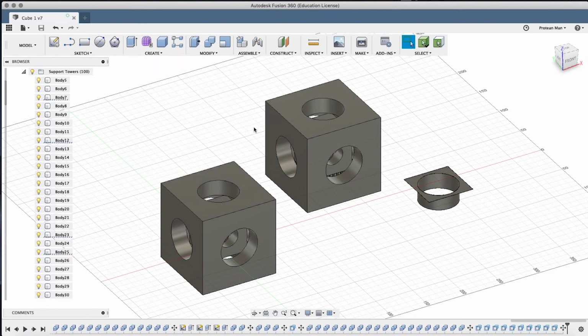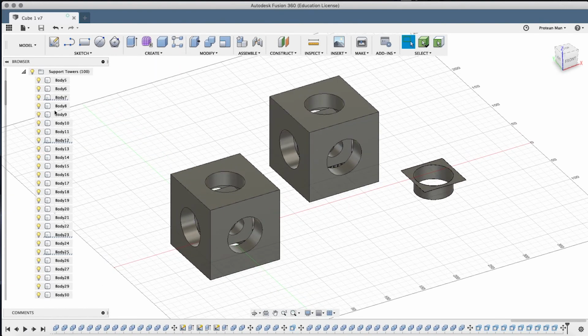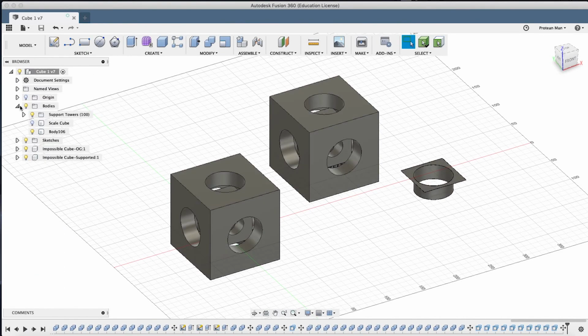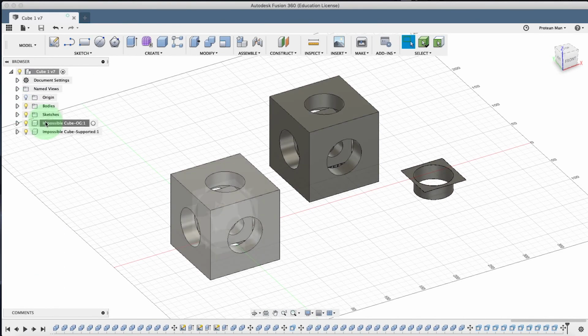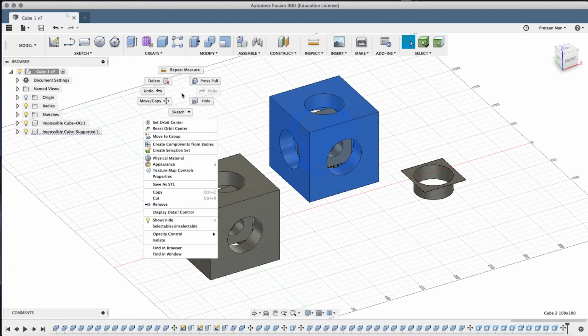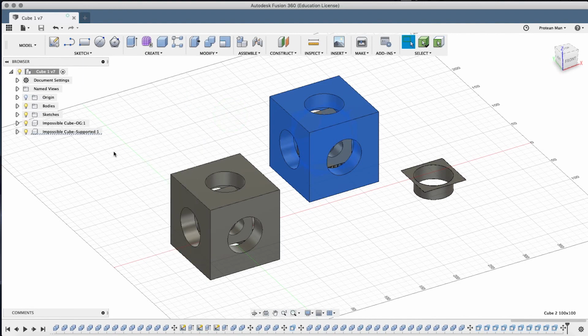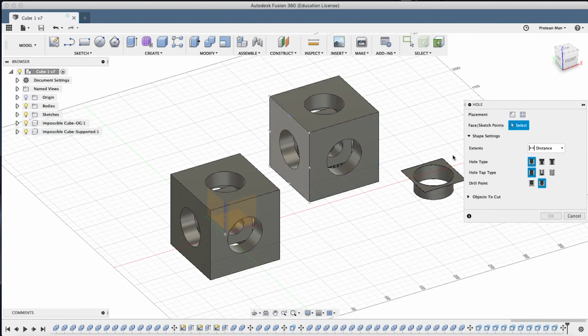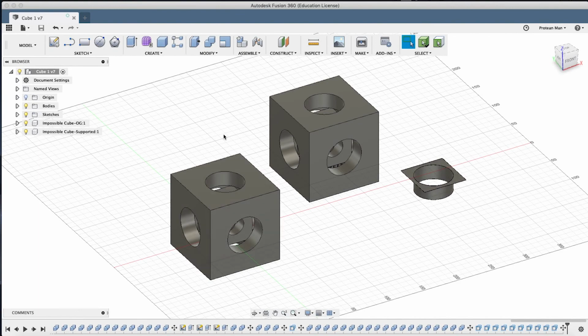But either way, to recap quickly, you've learned about components. Click an object, or multiple objects that you want to be one thing, one file folder. Click multiple bodies to become one object. That's a better way of saying it. So create components is right there, and components are a key thing. You want to use components in the end. You don't want to have a list of a million different bodies. You want to actually have components.